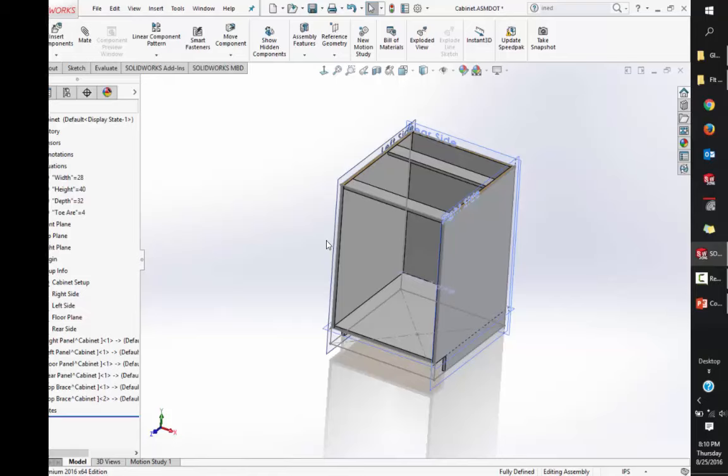Well, apparently, the assembly doesn't like my top-down design. And I now get to put in a nice little enhancement request to SOLIDWORKS going, hey, I really need to do this, all right? What I need is to be able to save an assembly that's got virtual components, but SOLIDWORKS is still detecting that it's referencing external files. I've already seen the fact that everything's held internally here. So my plan really falls apart at this point.